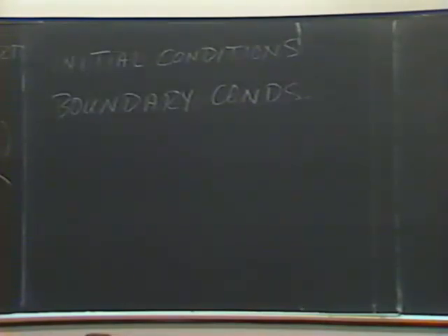I want to point out some of the important parts of this equation. First of all, you notice it requires the velocities and the concentration gradient, but it requires the velocities, and that means that you have to have accurate velocities at every point in the system, or if you're discretizing it, as it turns out that we do, at a sufficient number of points in the system so that you have a U and V known accurately. This is a term that gives you difficulty in the numerical solution, so you want to know those. You want those tied down pretty well.